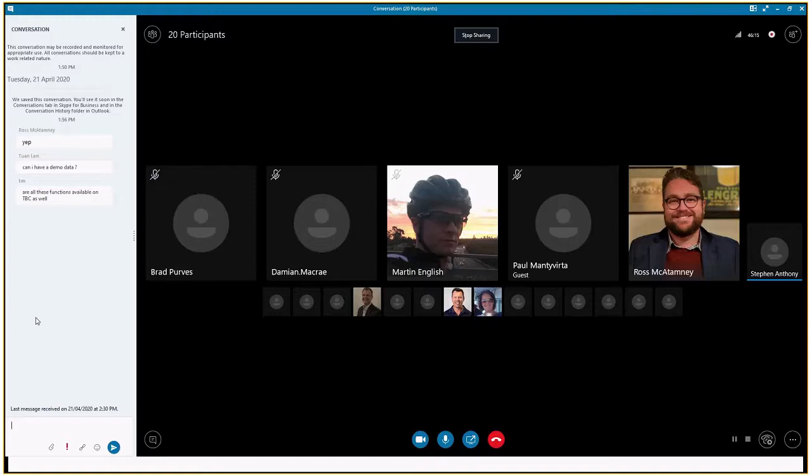Also with the sampling tools, there are a couple of basic sampling tools in TBC. In RealWorks, there's probably about 10 of them. And the topography-based sampling that I showed you, where I removed the last bit of noise off the road surface, is a bit more of a manual process in TBC as it stands.